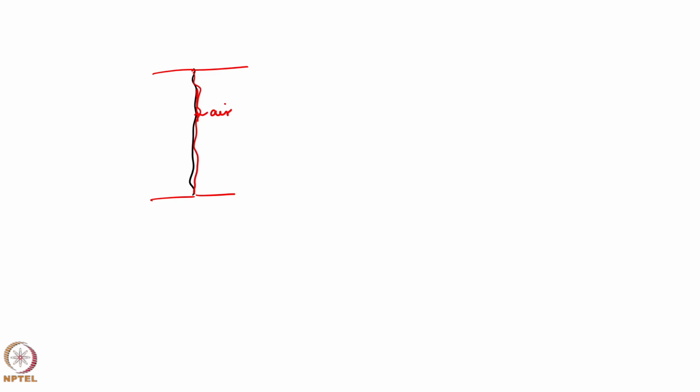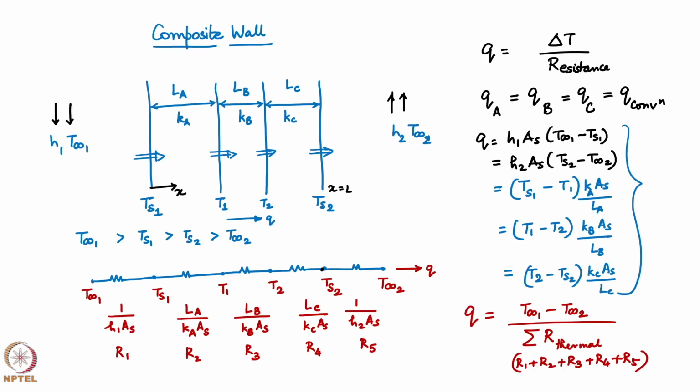Okay. What I am trying to say is, this thermal grease will become unstable after a certain temperature. So, maybe this might be a bottleneck in some application. Beyond 180 degrees, this grease is going to become useless. So, T 2 should not exceed 180 degrees.